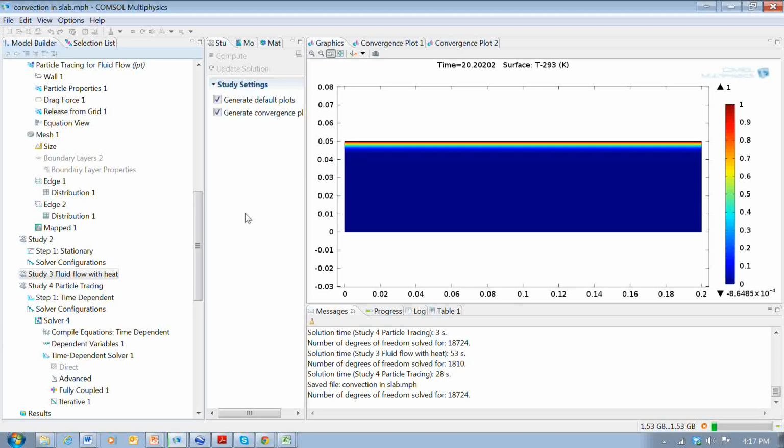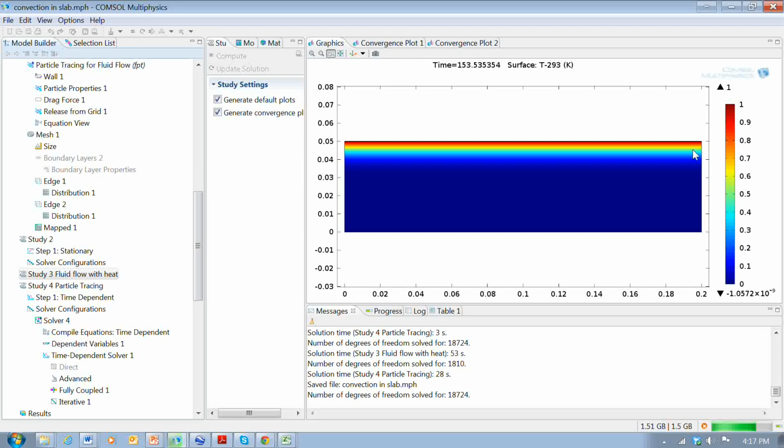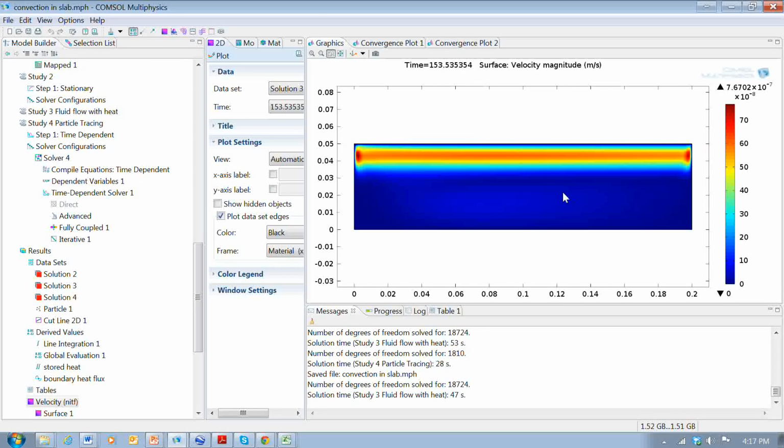And fluid, we're heating it from the top by 1 degree, and this is the time here in seconds. So where temperature is increasing, it's propagating down. And so we've seen this kind of pattern before. This is what you expect to get when you heat something by conduction. The heat propagates in, it makes this nice uniform band, and it's going as the square root of time, and so it's propagating in, but the longer it goes, the slower the front propagates in.